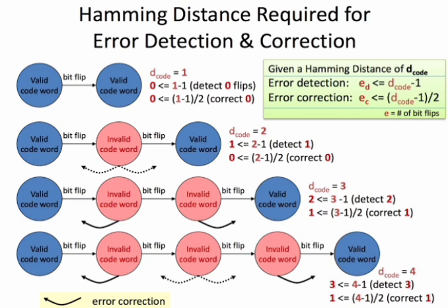The algorithm commonly used to perform this decoding operation starts with the computation of a vector called the error syndrome vector, or simply the syndrome S bar. S bar equal to Y bar H bar transpose. Based on the obtained syndrome, a particular error pattern will be selected by the channel decoder to correct the errors. Properties of syndrome. Property 1: the syndrome depends only on the error pattern and not on the transmitted code word. S bar equal to Y bar H bar transpose, equal to (X bar plus E bar) H bar transpose, equal to X bar H bar transpose plus E bar H bar transpose. Since X bar H bar transpose equals 0, S bar equals E bar H bar transpose. Property 2: all error patterns that differ at most by a code word have the same syndrome.